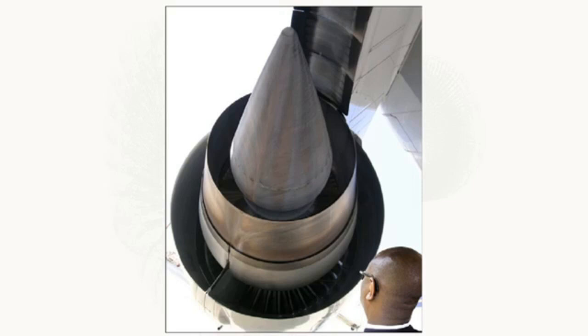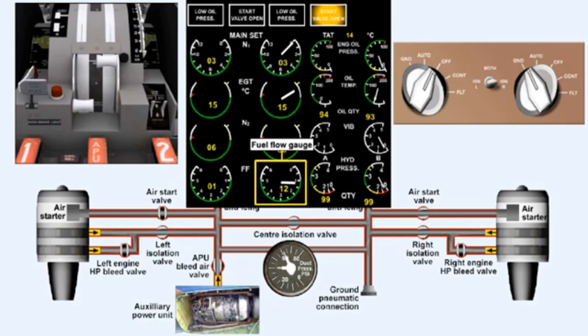Alternatively, if your starter crew trust you, and if it's safe for them to do so, you could direct them to the rear of the engine, and, having selected relight, ask them to listen for the asynchronous ticking noise which two high-energy igniters make when they're feeding spark to two serviceable igniter plugs. Another cause of a gas turbine engine failing to start could be a lack of fuel, but this is fairly unlikely to occur on an engine that was working perfectly when it was shut down. A check of the fuel flow meter when the start lever is operated will give you ample evidence of whether fuel is being fed to the engine or not.